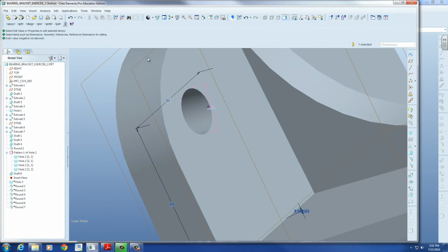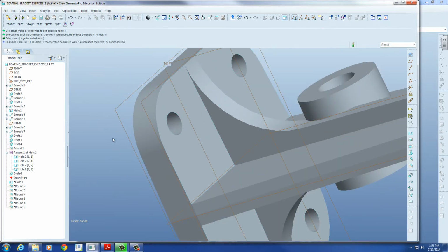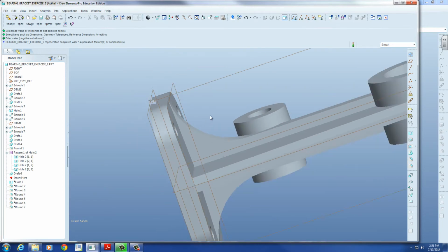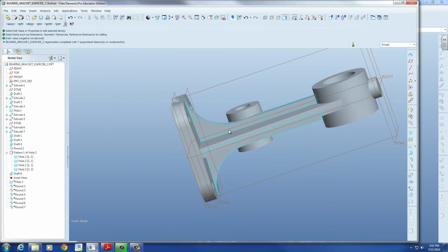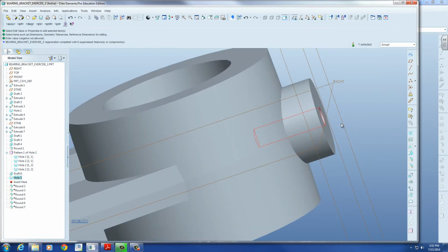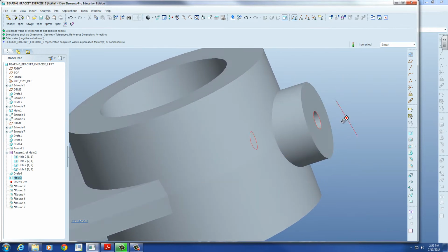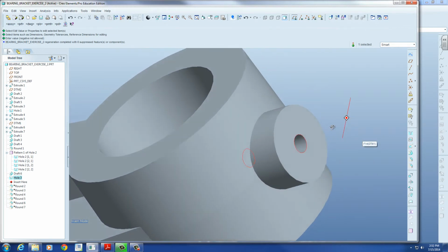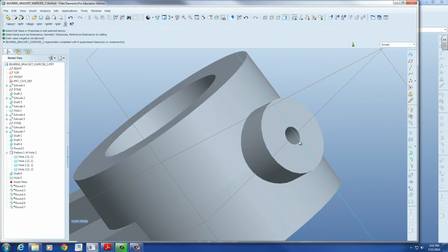Could we, if the problem is a lead-in, could we create a small chamfer? Yes, absolutely. That's normally the way you want your draft. It's pulled this way because you want to put those in there, but you don't want to do that with all these features inside here. That hole is here. We need to drop this one too, right? Where are we going to drop this one from? The top. The top, and let it get smaller. It's better to have interference in a plastite screw than have looseness.